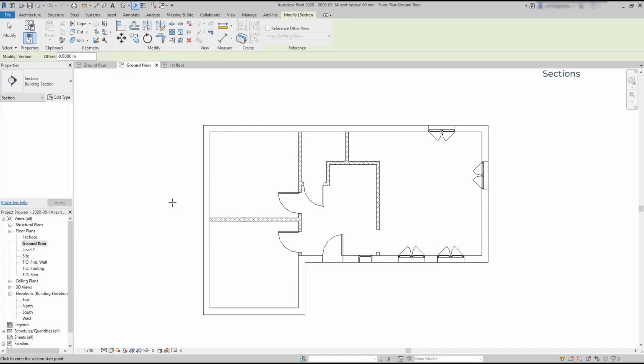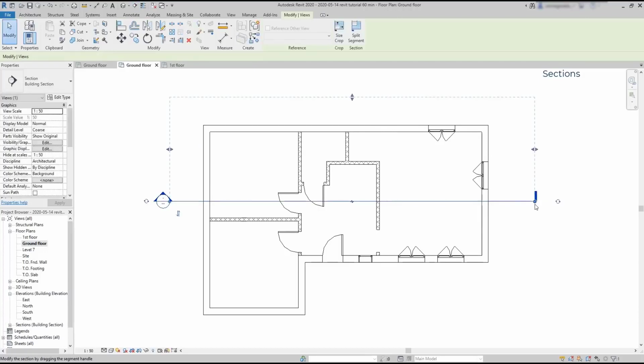To create a section, I need to insert 2 points. I click here and then put the second one on the other side. And note that sections don't necessarily have to be horizontal or vertical. It's also possible to make a diagonal one. But for now, let's just leave it simple and logical. I mean, for this situation, of course. This rectangle with the dash border is my view area, which can be controlled with this grip. With this icon at the left, I can switch my view direction.